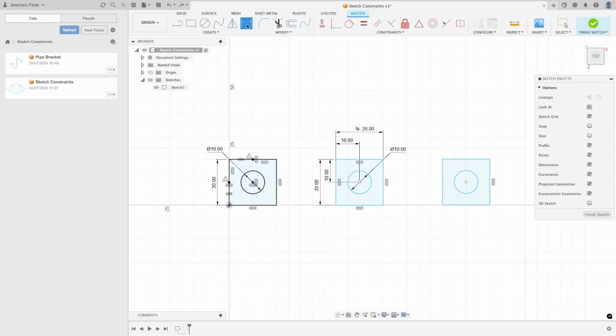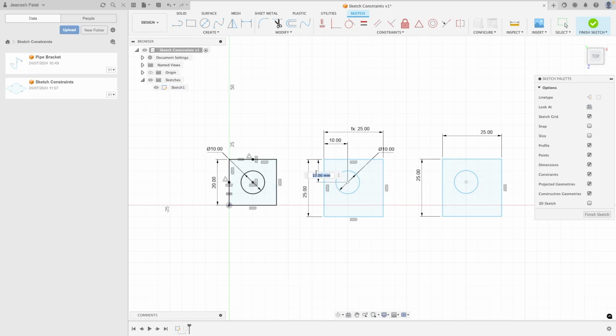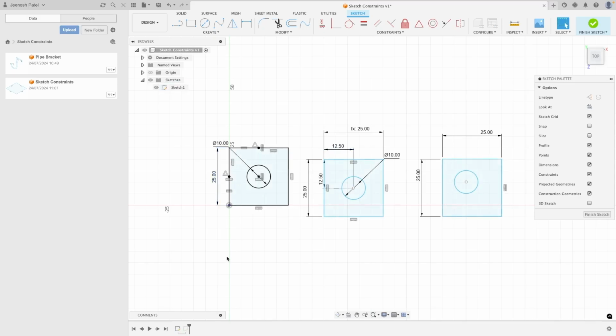If I have to change the height of my first object, you will see that as there are no constraints, I have less control over the object itself, and will have to individually change all of my dimensions to ensure my part behaves how I need it to. The second one, when changed, behaves slightly more predictably. However, if I require the circle in the center to adjust, I have to manually dimension each direction. The only one that behaves like I want it to is the fully constrained sketch, which adjusts automatically when I change the dimension, and does not move freely.